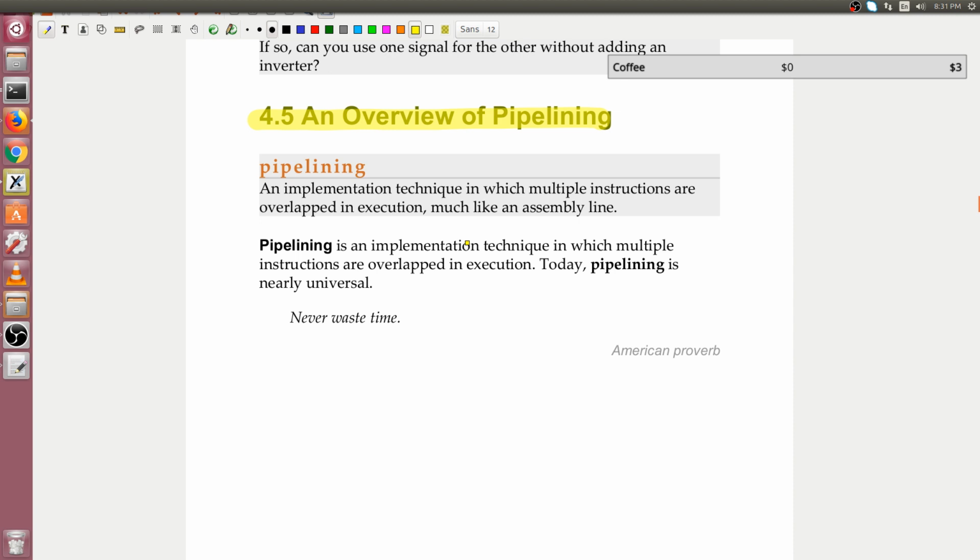And so you started out with things as simple as a 5 deep pipeline. And then you moved a little bit more forward and you had things like a 10, a 12, a 14 deep pipeline. And then you went a little crazy and you had something like a 22 deep pipeline. But you have to remember that a 22 deep pipeline assumes that you have that level of instruction level parallelism. The hazards become a real pain once you have to handle them for 22 instructions in flight at the same time. And then you also have to worry about, well, I'm adding little delays in 22 different spots for each of the pipeline stages, so that gets messy.